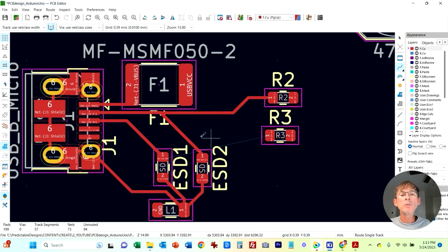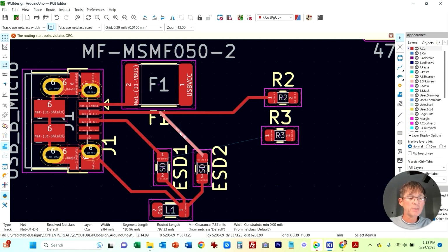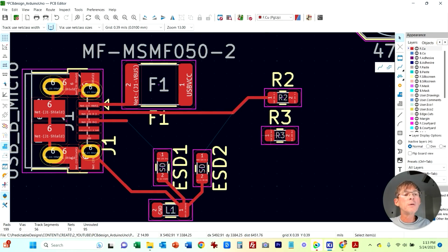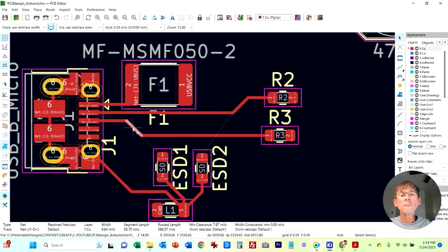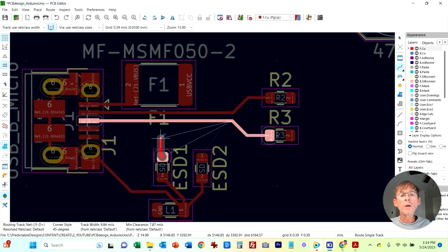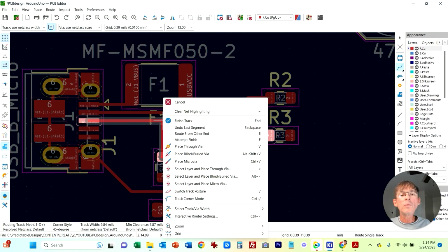What I think I'm going to do is disconnect the ESD, and we'll via for those. We'll do a via. Like that. There, these can be kept really similar. And now we just have to do it via here. Via. Actually, I'm going to not do it that way. Let's just pour out and then do.